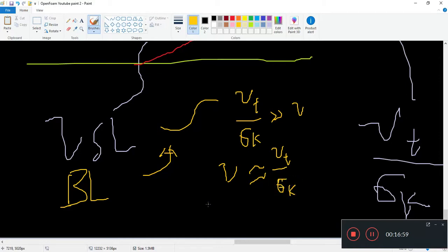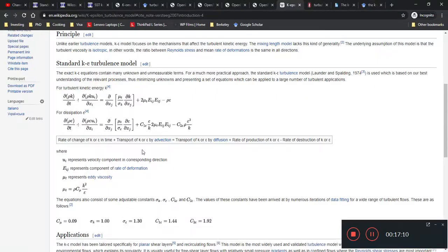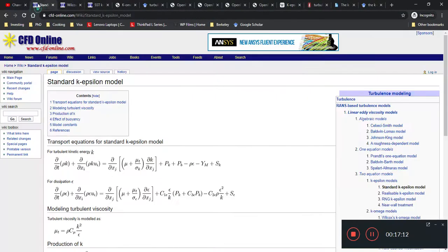So what do we do then? Do we have to change the equation every time we switch from here to here? For practical purposes, no. So that's why in CFD code we tend to just keep this here and not neglect it, so that we can use one equation to solve in the bulk region and also in the boundary layer region.